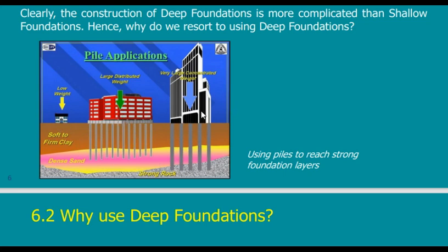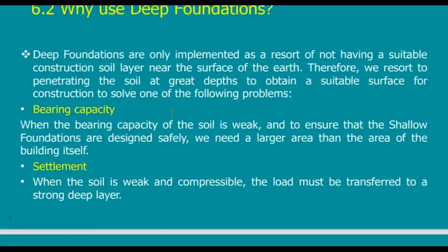If I leave this case and go to the other case, I have a very high-rise building, with very, very big loads. I cannot just put normal piles. My piles should be very, very big. I may use very big piles, usually we call them shafts, so that they can reach very deep layers to reach the rock, so that I ensure that with this very high-rise building, I don't have more settlements than the allowable. So this is my way of thinking.